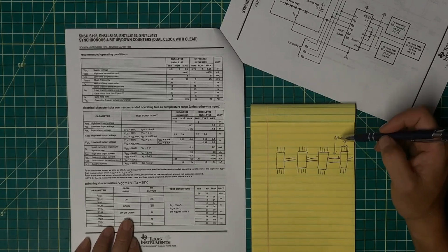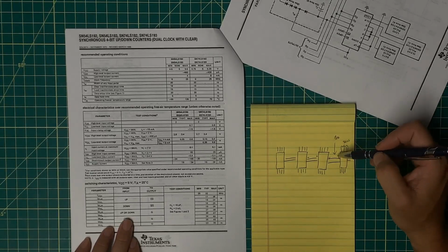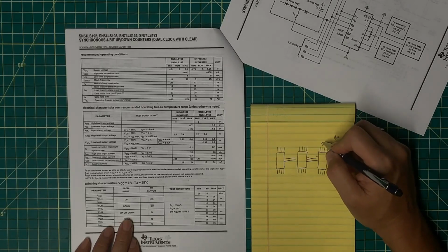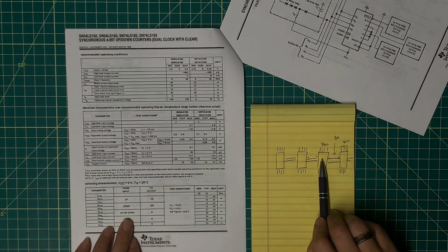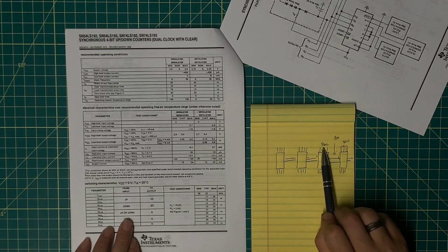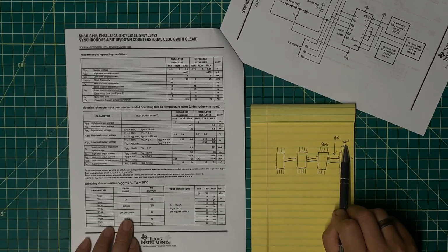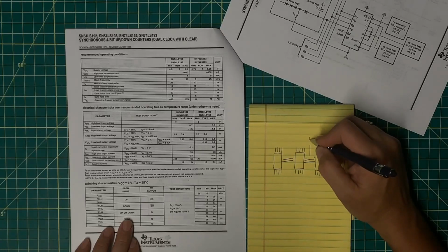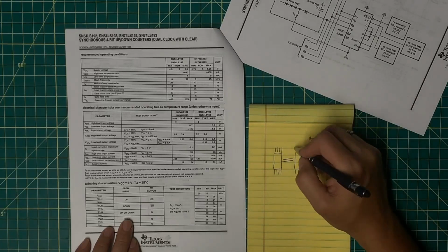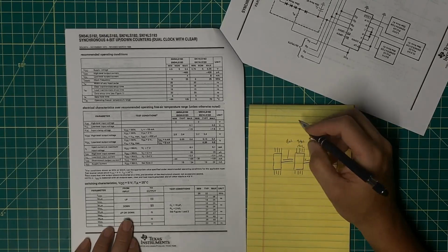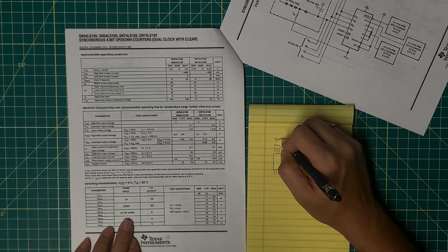Now, what's interesting is that if this triggers an up count over here, it's really 30 nanoseconds here, which now becomes the relevant number because this 18 nanoseconds plus this 30 nanoseconds is my high water mark. These outputs are settled long before these outputs are. And again, if I work my way up, it's 18 nanoseconds here, another 30 nanoseconds here, another 18 nanoseconds here, and then another 30 nanoseconds here.